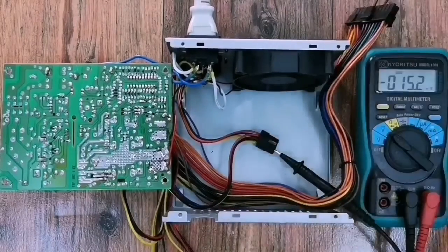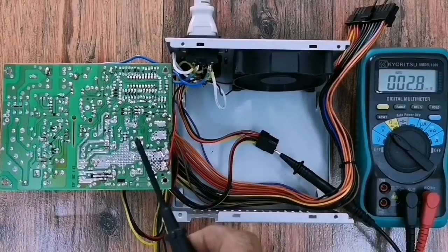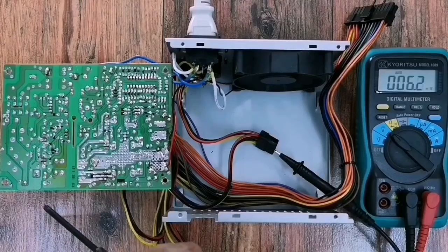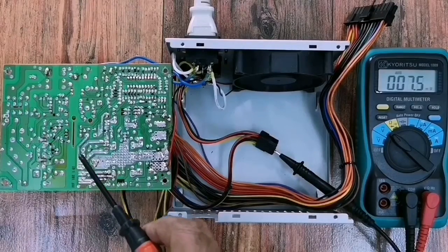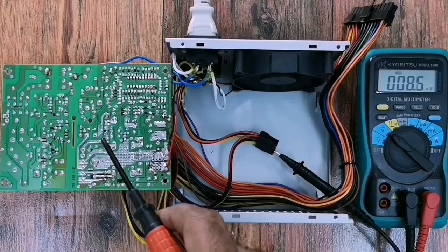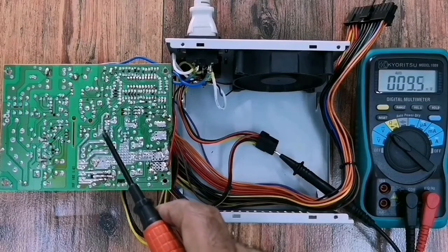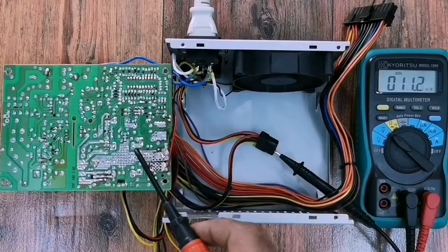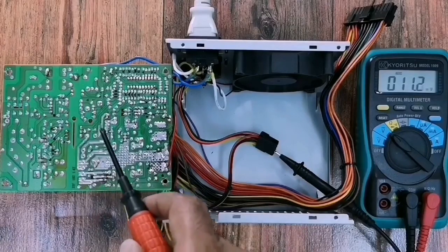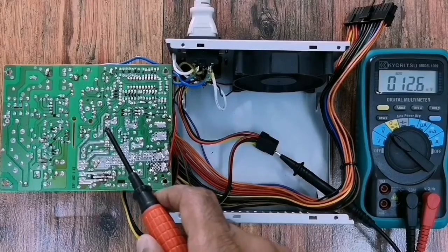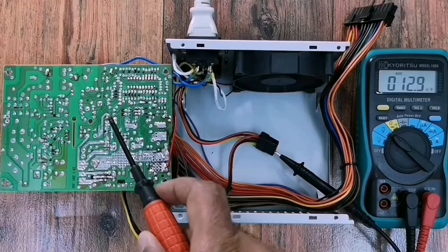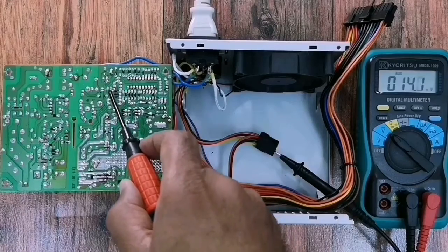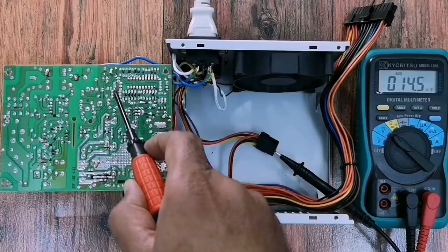Another important tip here: using the right test equipment is very helpful to check some types of failure modes. Just think, if I didn't use the oscilloscope at this particular fault and just used the multimeter alone, guess how long I could have taken to find this issue. Especially, we don't have the drawing to know the right voltages at transistor pins.